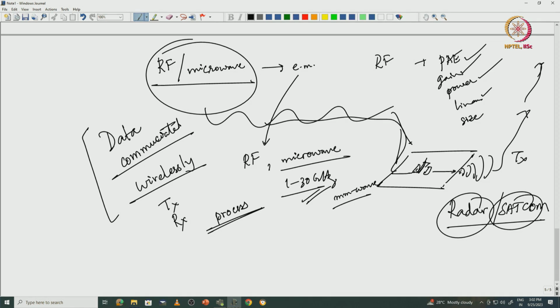Satellite communication uses something called a transponder, a transmitter and a responder, slightly different from a transceiver, by the way, which is a transmitter and receiver used in cellular infrastructure. So they all use microwave devices for transmitting and receiving. The antenna is used of course, but to process the signal, to amplify the signal, you need these microwave devices in a microwave circuit. So these are some of the very broad and important applications of microwave electronics. But other than that, there are abundant applications. You have remote sensing, you have maritime communication, you have radio astronomy.